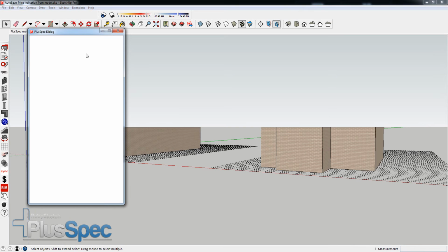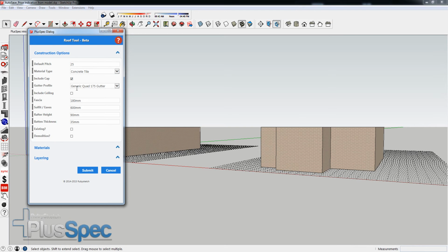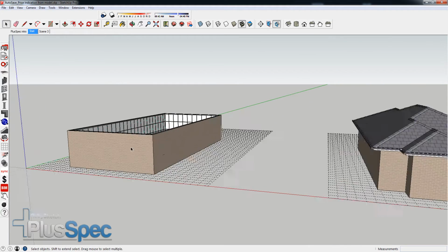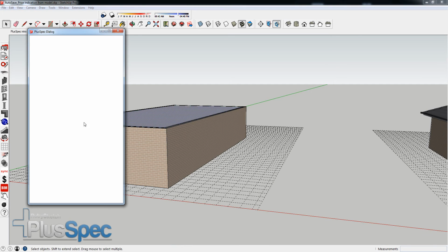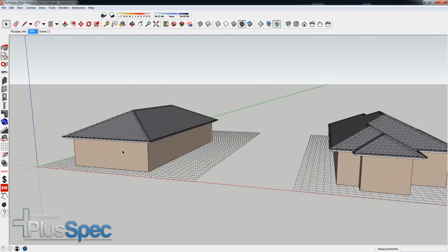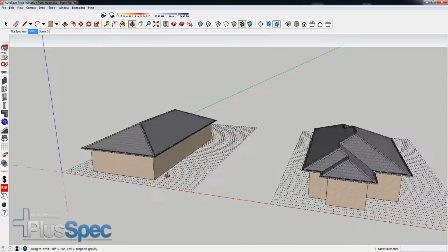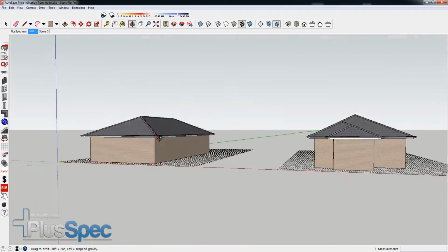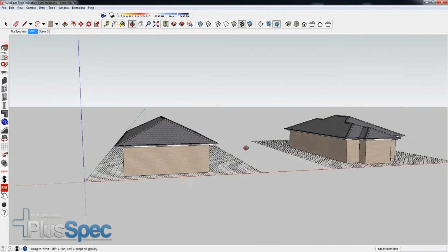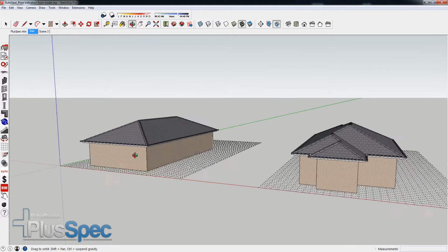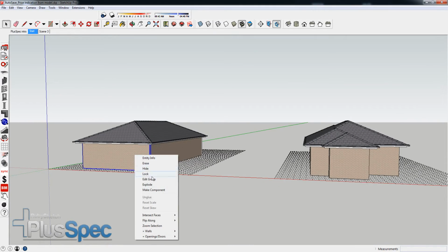And I'll just use standard concrete tiles, and same pitch, same overhang, cement. Okay, and this little box over here, same type of roofing. And what I can do now is, I'm looking at a small little house, single story. I think for the purpose of the exercise would be more than adequate. And what I might do is just go through how many square meters are in these houses. So we just generate a floor face from the walls.